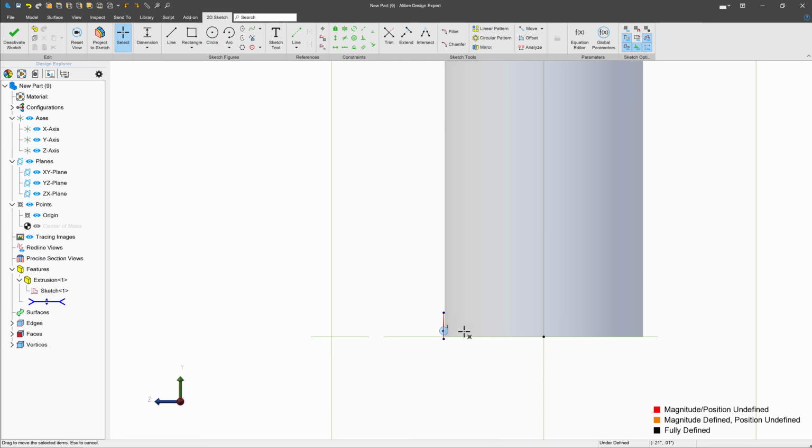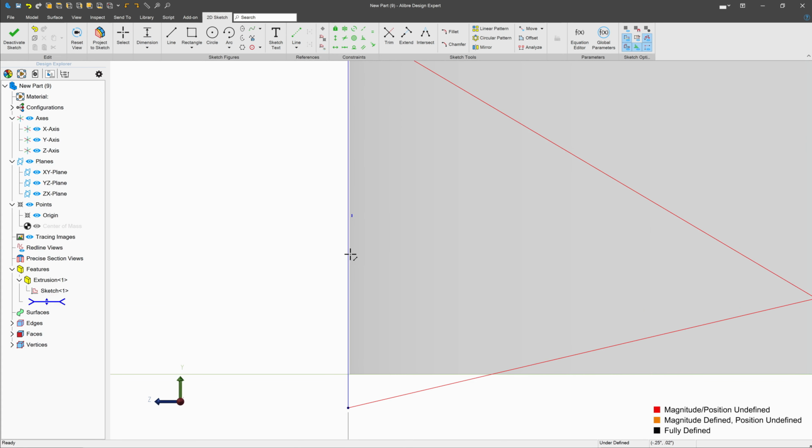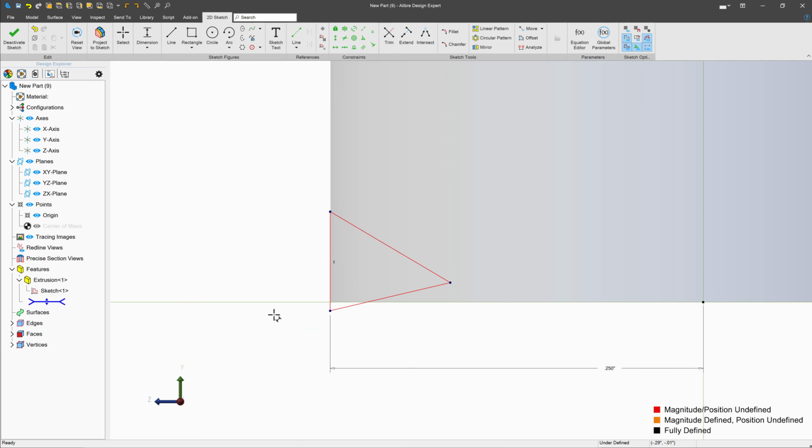In fact, you know what? Let's do that because I already showed you how to do an additive revolve. So we'll have this. I'll have this be 0.2501, and I'm adding that 01 just so it goes a little bit above the face, and that might help the kernel decide what the good geometry is. Look at this dimension here of 0.0625, sounds good. We'll make sure that we are equal here and here. And we'll give this a 60-degree angle.